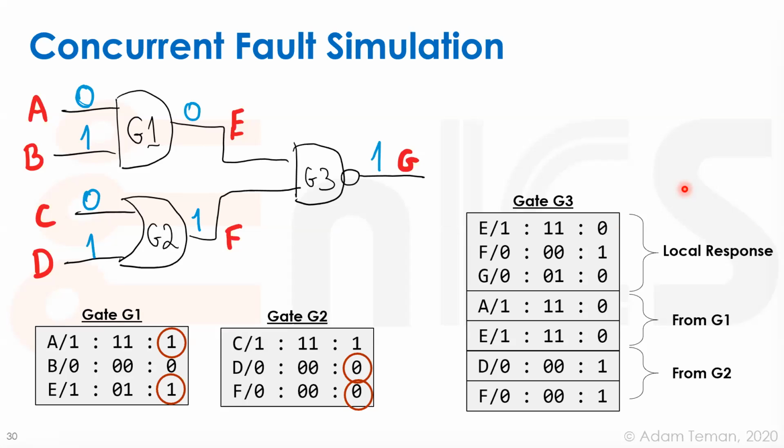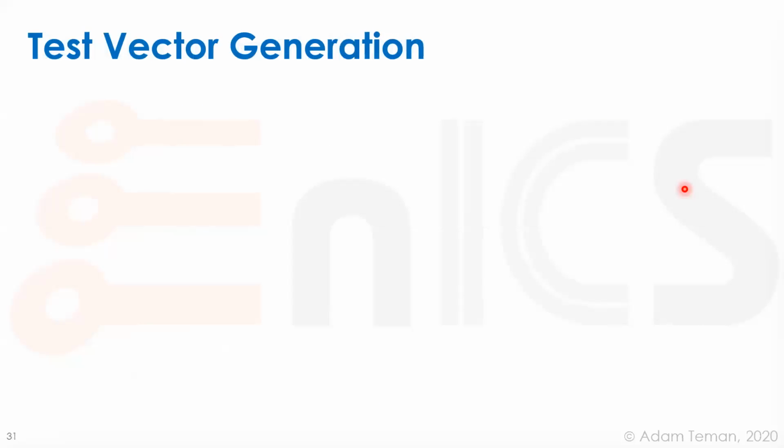Okay. So we discussed fault simulation. First of all, we made a fault model. Remember, I showed you a few things before. We said there's a fault model, okay, we saw that. Then we said, if we have a fault model, how do we do fault simulation to see which faults a certain test vector tests? That we just discussed in some algorithms how to do it. And the next stage, we have to say, okay, now how do we generate these vectors?